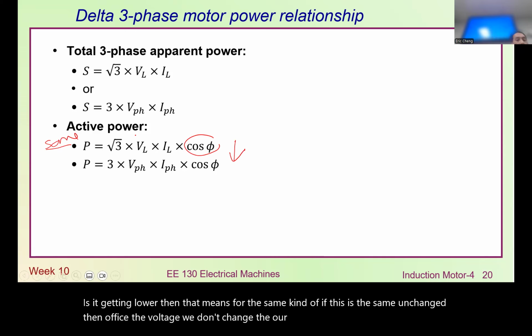That's simple Ohm's law to do that. And then we have the resistive part. So for that resistive part, we measure the real power during that time. So 400 volts divided by this current, then we get this resistance. But this resistance apparently may look like R1, but that may not be the case.